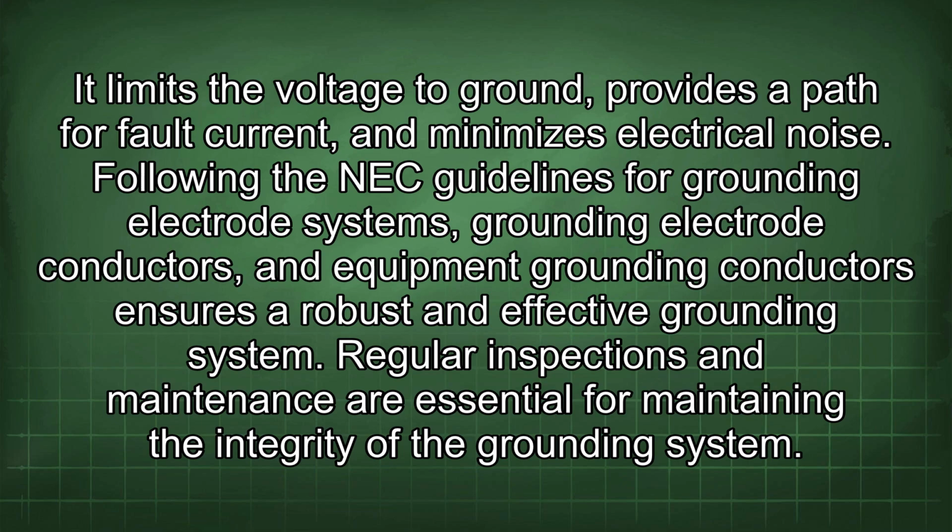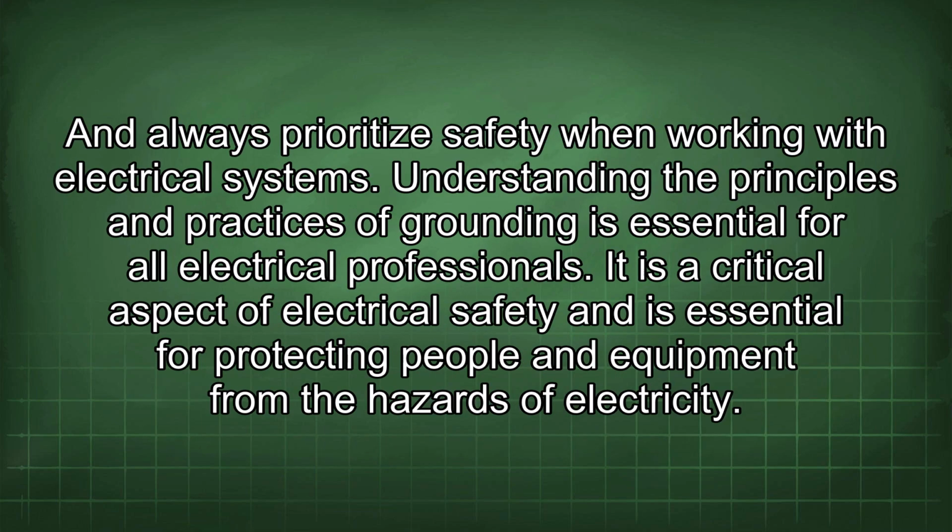Following the NEC guidelines for grounding electrode systems, grounding electrode conductors, and equipment grounding conductors ensures a robust and effective grounding system. Regular inspections and maintenance are essential for maintaining the integrity of the grounding system, and always prioritize safety when working with electrical systems. Understanding the principles and practices of grounding is essential for all electrical professionals. It is a critical aspect of electrical safety and is essential for protecting people and equipment from the hazards of electricity.